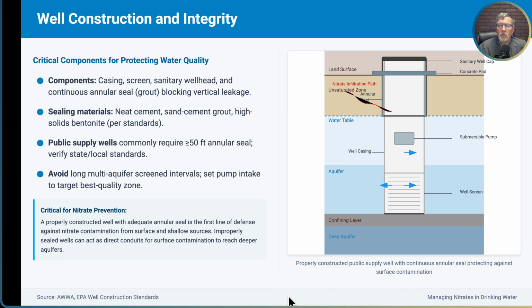So you're going to want to construct a well based on geology and hydrogeology, not based on the standard. Those are just recommended minimums, and you don't want to do that without thought to the geology, because you may end up with a useless well or a contaminated well, and you spend all that money. So why not do it right and get the seal right? So if it means hiring a geologist to come in and look at it, well, so be it. I always like to say geologists are cheap, so hire two.